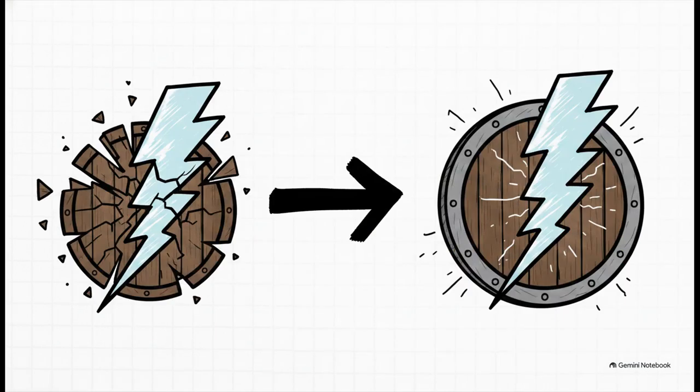But here is where your systems studies become absolutely vital. If your engineering studies calculate a potential fault on the grid of 20 times the normal current, you absolutely cannot use a 5P10 core. Actually, let me be stronger about that. It will fail. At 12 or 14 times normal current, a 5P10 core behaves abnormally, and your relay won't trip. You must upgrade and specify a 5P20 core so that the relay stays perfectly accurate at that extreme 20x limit.